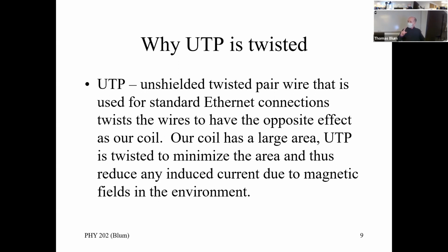The coil tries to magnify the magnetic field by having all of the magnetic fields in the same direction and giving you a big effect. The wire in an Ethernet cable is twisted, and it makes the magnetic fields oppose each other and cancel each other out.